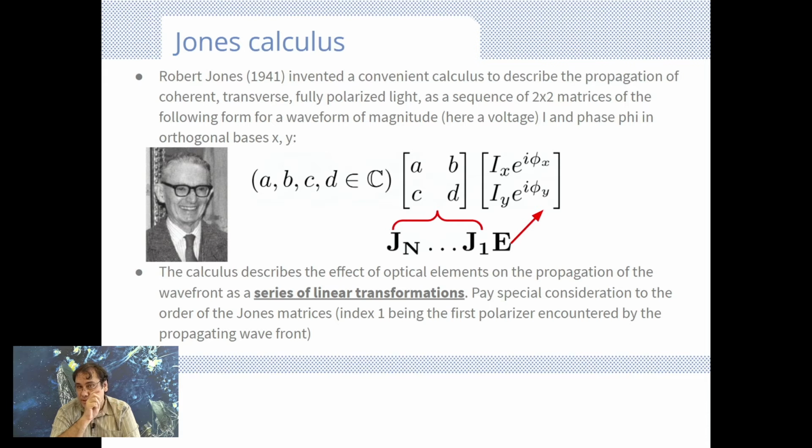If you multiply all these different complex 2x2 matrices together, you get this final matrix. Now, these are all just describing linear transformations on the signal, and we calibrate them one by one, starting from the effect that is closest to the measured signal.